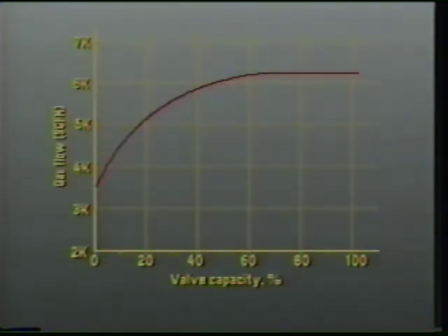In this example, the point on the curve reflects gas flow in standard cubic feet per hour, SCFH, at 10% of the valve's total capacity. The slope of the curve at this point is indicated by a tangent to the process curve at a given point.